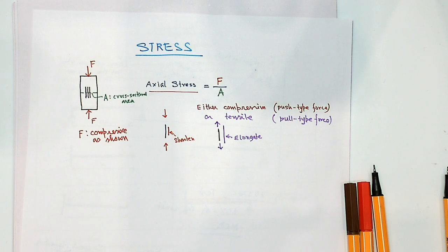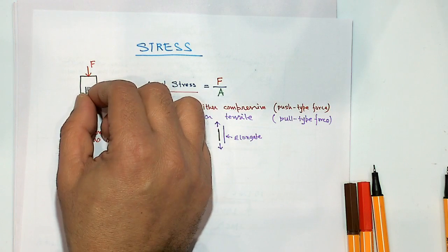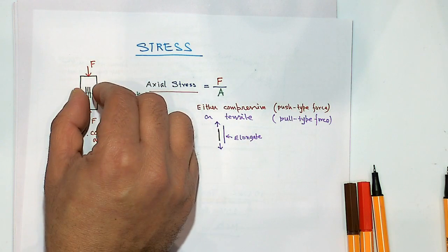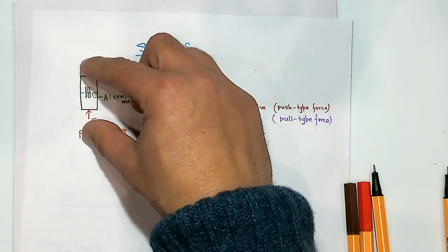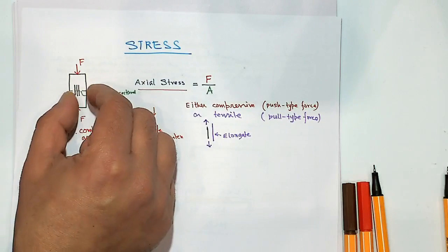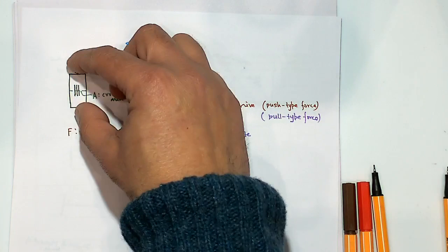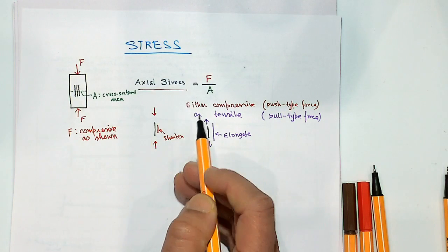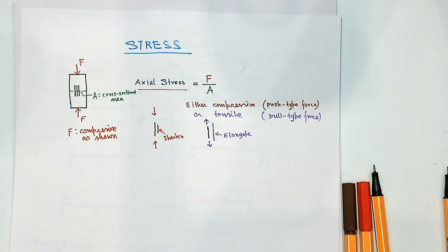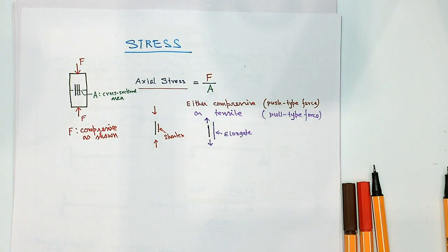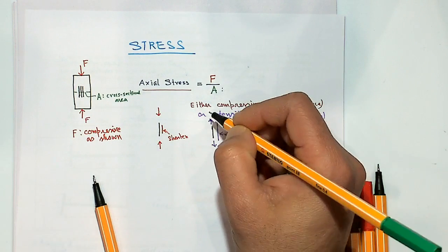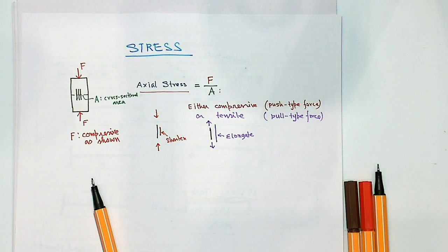That's due to Poisson's effect. The strain that happens is true: in this case the member will fatten up and the cross-sectional area will increase, and if you put tensile load, the cross-sectional area will decrease. But in calculation of the stresses, we never take the reduced or increased cross-sectional area. So this nominal cross-sectional area is always used. A is the original cross-sectional area.